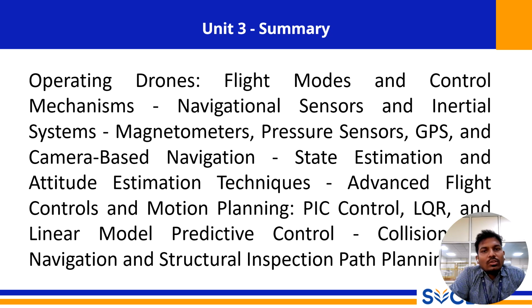The drone's ability to navigate and stabilize itself starts with its inertial system. At the core of this is the inertial measurement unit (IMU), which typically contains two sensors. First, accelerometers are the fundamental device that measures specific force, which is the combination of the aircraft's own acceleration and the constant pull of gravity. By sensing these vector forces, the drone can determine which way is down.